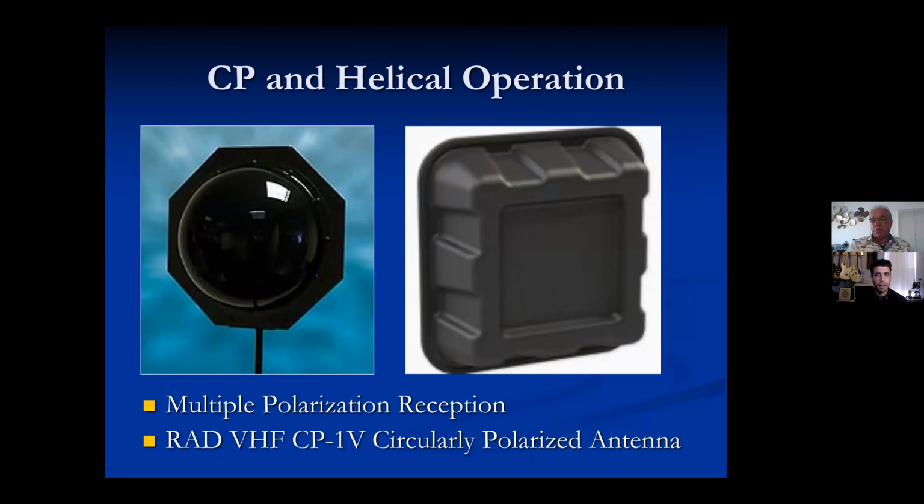Sure. What's the question? Well, I think the question is, can you passively split to both CP and helical antennas simultaneously? So I'm imagining this was for IEM transmit. And I guess in my mind, when you start doing IEM transmit for multiple antennas, that's where you might run into a multipath issue. Okay, so multipath would refer to a wireless mic receiver antenna and the RF signal from one microphone bouncing off the wall, flipping in phase 180 degrees, and then meeting itself and canceling out.